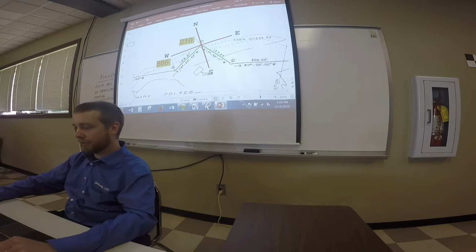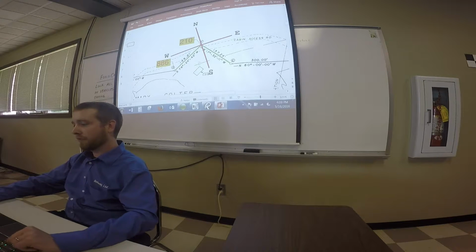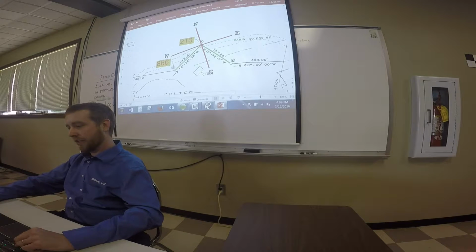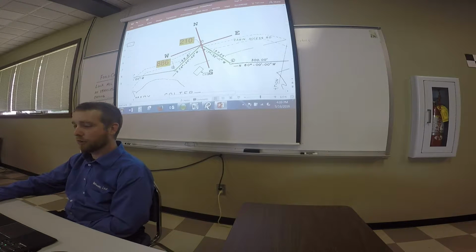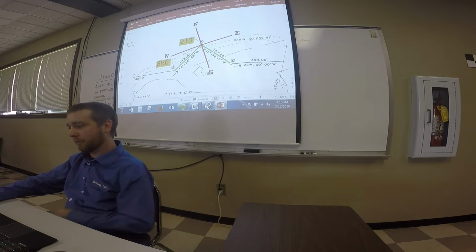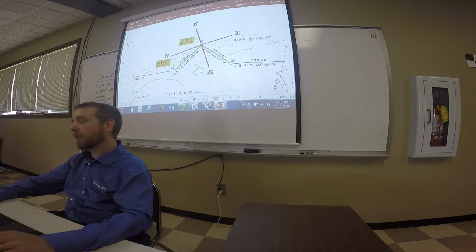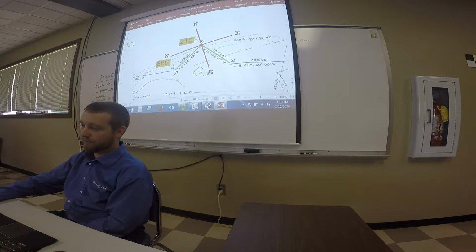All right, so the green lines here show the lines we want, and the angle in between the green lines is the angle we're looking for. Now you'll see that this line is southwest, and this line is going northwest. That's because it's starting at this point and going in this northwest direction. Well, north 17 west just so happens to be south 17 east. It all works the same way, depending on what direction you're going. Same with this one. This one is south 74 west. If you extend that line out, you also get north 74 east.